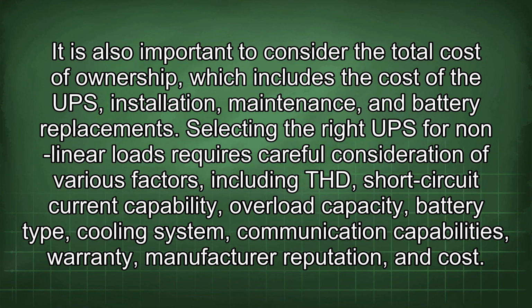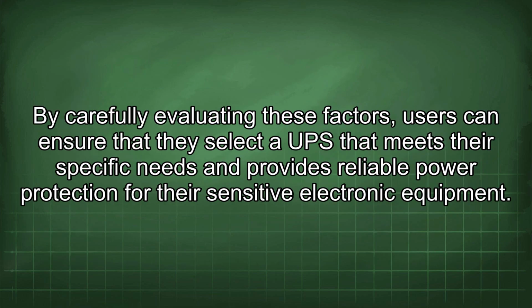Selecting the right UPS for nonlinear loads requires careful consideration of various factors, including THD, short circuit current capability, overload capacity, battery type, cooling system, communication capabilities, warranty, manufacturer reputation, and cost. By carefully evaluating these factors, users can ensure that they select a UPS that meets their specific needs and provides reliable power protection for their sensitive electronic equipment.